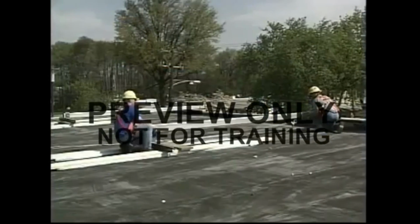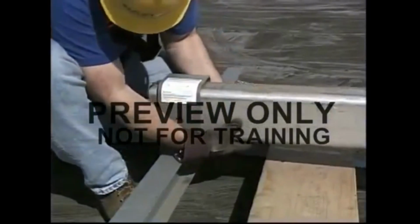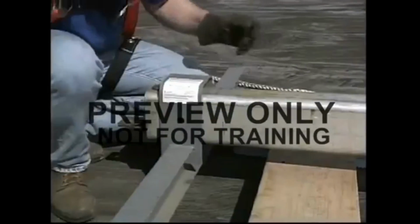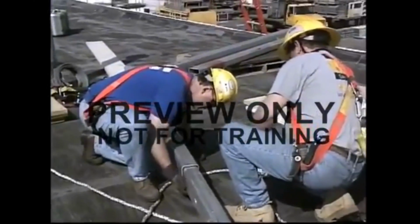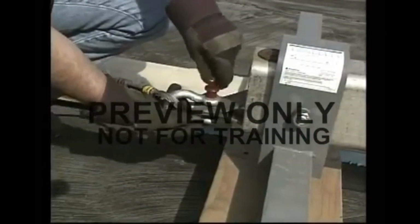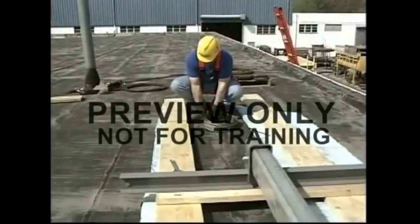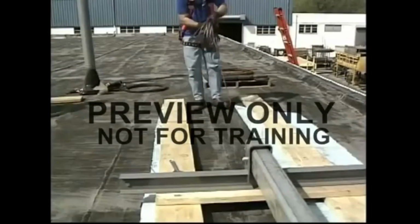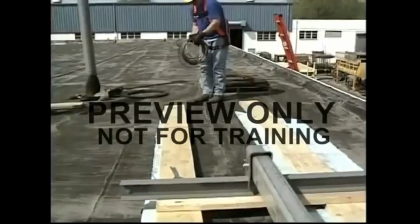For best results, outrigger beams should be placed perpendicular to their supports, unless it is determined by a scaffold expert that it is safe to attach them at a different angle. The beams should then be stabilized with ropes known as tiebacks. Like the scaffold itself, the tiebacks must be strong enough to support the maximum intended load of the scaffold.